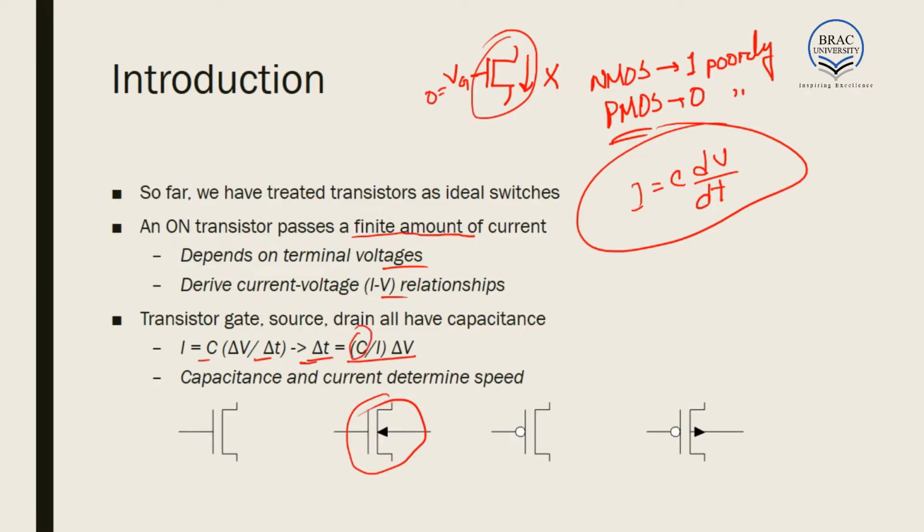This delay is caused by the capacitance, which is finite in amount, and as we can see from the expression, the lower the capacitance, the lower the delay. We want the delay to be 0 or as low as possible, but that is actually not 0. So this is also a non-ideal component which we need to consider. We'll be learning where these non-ideal components come from and what design rules must be followed in order to decrease them.